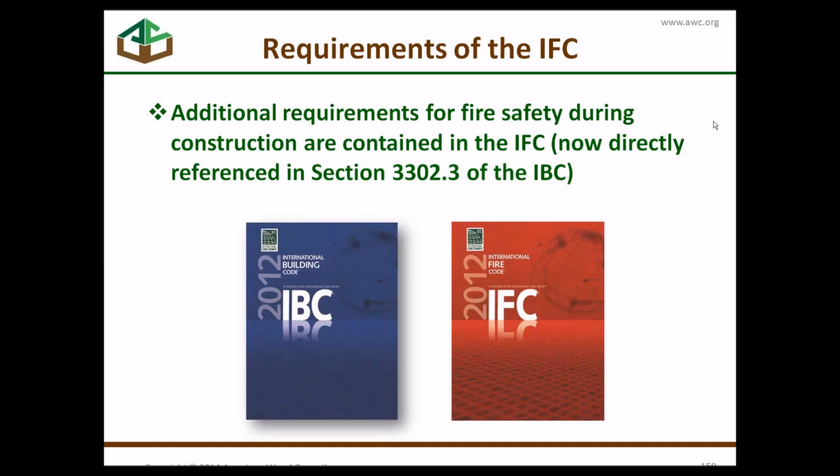Now, something has happened in the recent edition, the 2012 IBC, that sends you directly to the IFC here. So you have a new provision in the International Building Code that sends you directly to the IFC for a whole list of requirements there of precautions during construction. This is a new requirement in the IBC in 2012. And so therefore, what that does is whether you use the IFC or not, these provisions are referenced and they're enforceable, and they should be followed in the IBC.